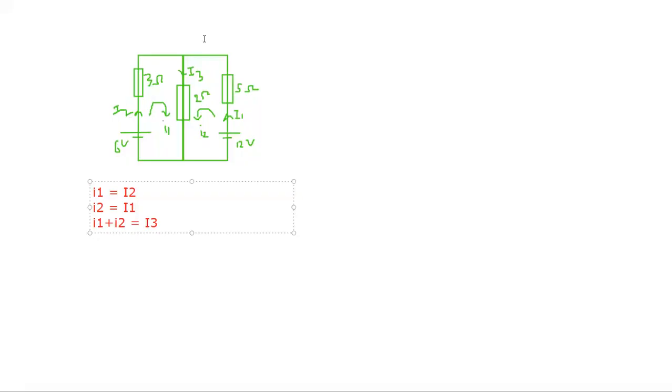Now the second step is to mark the voltage drops. Current is flowing from up to down, so this side is positive and this is negative. Current is flowing from down to up, so this is plus and this is negative. Now write the values of these voltage drops or rises. It is 3 into I2 according to Ohm's law. The branch current is capital I2 and the resistance is 3, so the potential drop or rise, whichever it may be, is 3 I2.